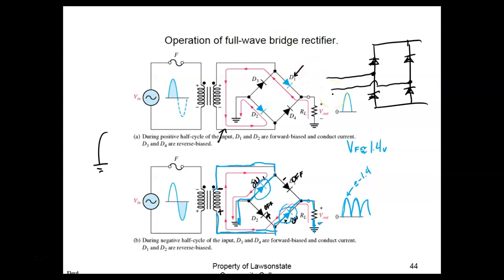So if you look at a schematic, D is used for diodes, T's are used for transformers, L is used for inductors, C is used for capacitors, U is used for integrated circuits, either that or IC. They like to abbreviate these schematic symbols with one letter, and then they'll put a number beside it. So like D1, D2, D3, D4.